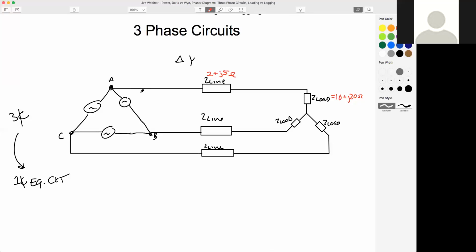We're going to go, I'm just going to pick 480 volts. We're going to say this is a three-phase. So the problem I'd say a three-phase 480 volt delta connected source. Notice I didn't say line or phase, right? Anytime the problem says three-phase, the next voltage, unless it says phase, you assume it's line, okay? So you're going to assume that's going to be your line value unless it says the phase to neutral or the B phase to neutral voltage.